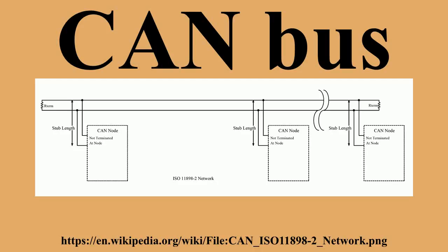The node with the lowest identifier transmits more zeros at the start of the frame, and that is the node that wins the arbitration or has the highest priority. For example, consider an 11-bit ID CAN network, with two nodes with IDs of 15 and 16. If these two nodes transmit at the same time, each will first transmit the start bit, then transmit the first 6 zeros of their ID with no arbitration decision being made.